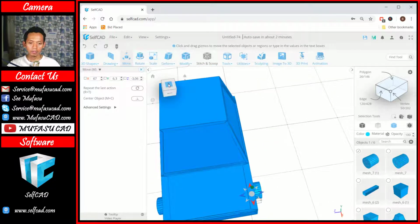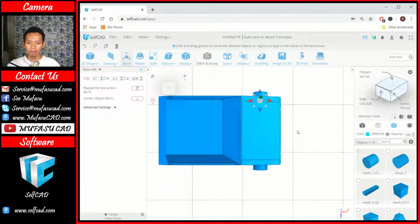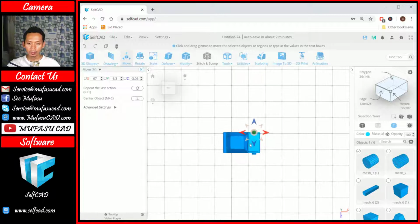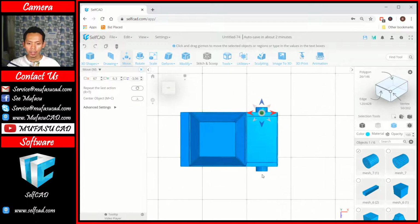Now you can change to top view. We can change again here to orthographic projection. You can zoom in, and I will select these two cylinder objects, and then you can press the Ctrl button and use this right axis. We copy to the bottom. Okay, this is for the tire.